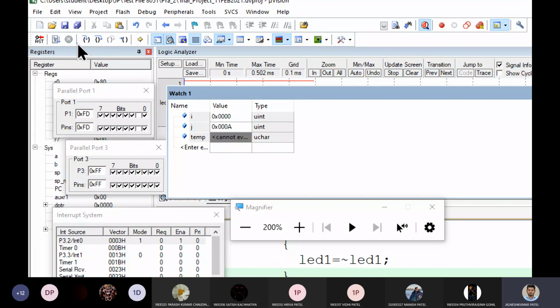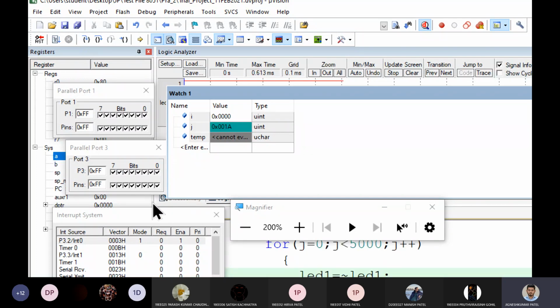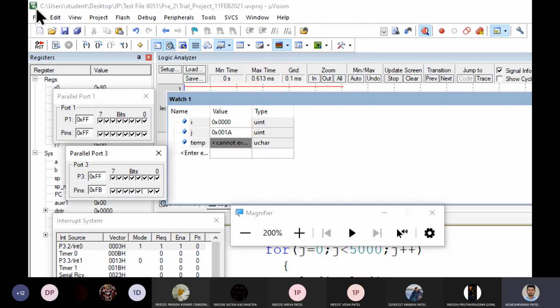So this is my continuous task, that routine task. It is right now in a for loop, so it is incrementing j continuously. No interrupt, so it is doing its routine task. Now I'm going to ring a doorbell. How? I'm going to give a falling edge here by writing this bit, pin 0. So I'm giving a pin 0.